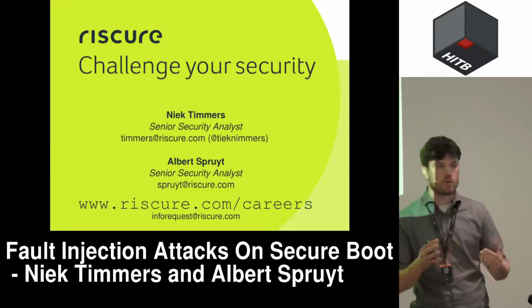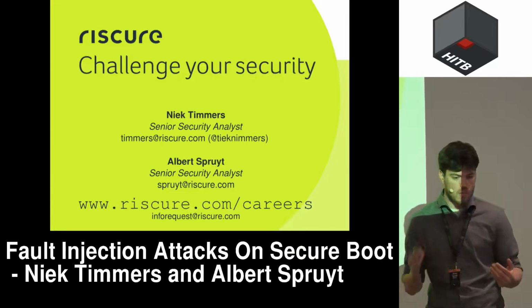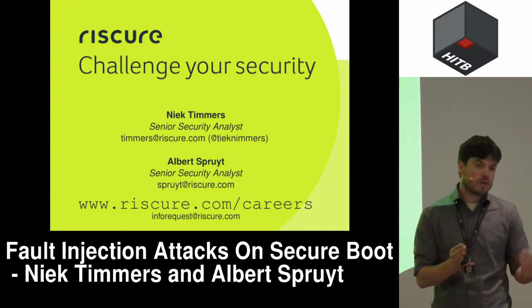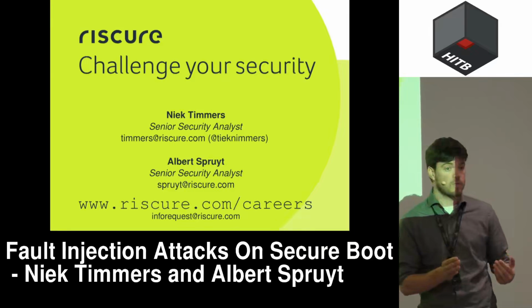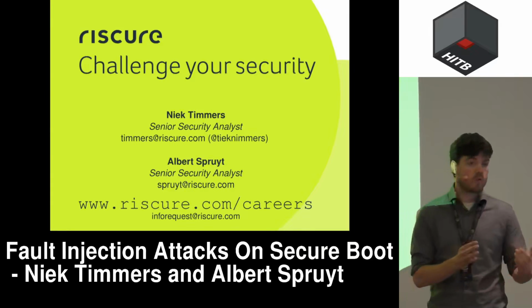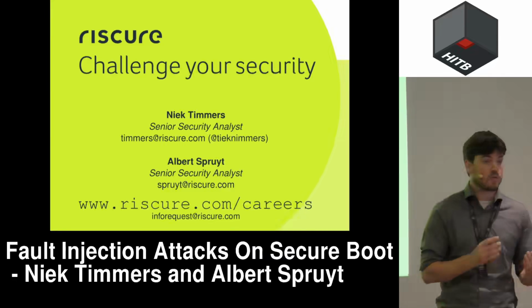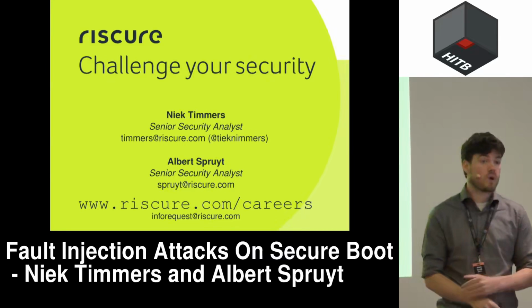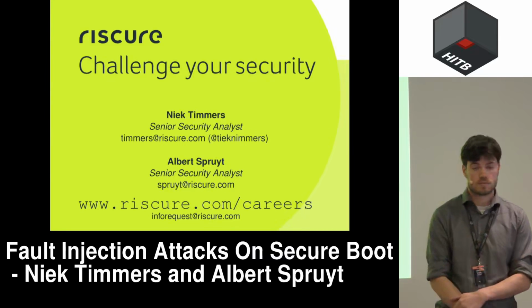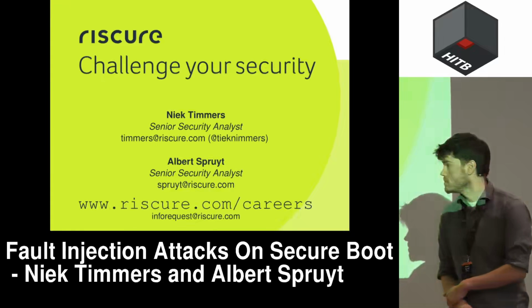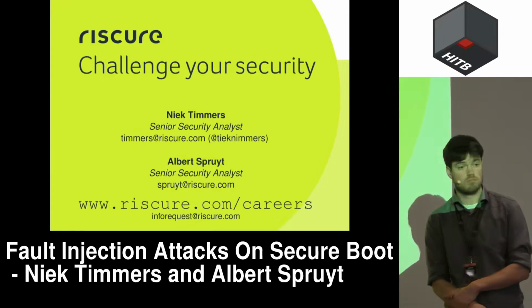So basically you need all your normal interfacing stuff, but it's also probably a good idea to have an oscilloscope ready, because you also want to take power measurements to determine when the best moment is to inject a glitch. Maybe after the talk we can talk more about details.